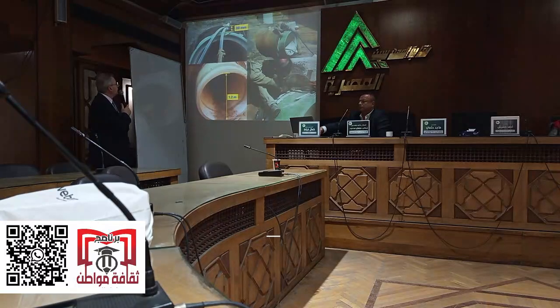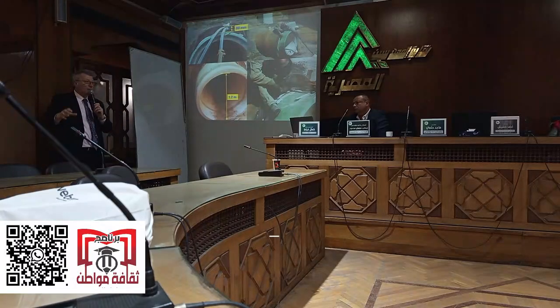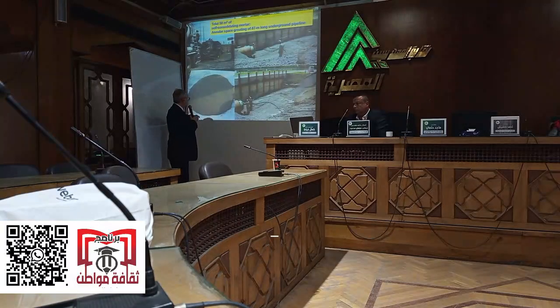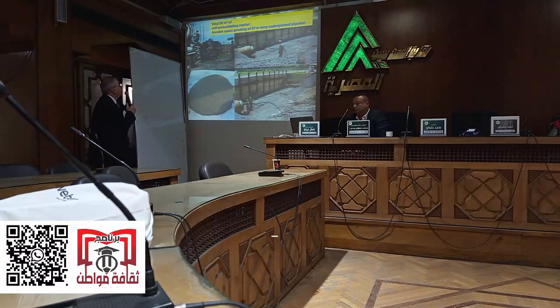So for the penetration, you can see the annular spacing at the top, 80 millimeter. It was inserted as far as possible, and then they started injecting and bringing it back, filling that annular spacing. And then when they were finished, so this is the slump flow. Again, it's a mortar, very stable and very flowable, and a total of 50 cubic meter of concrete was used to fill that annular spacing. The grouting was 87 meters in length, and the trial was very successful.